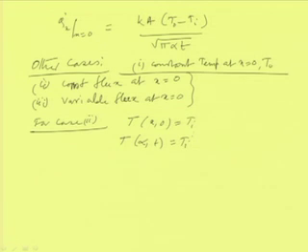So, there is no problem, these are not going to change. T at t equal to 0 is equal to T I, that is the initial condition, and this is boundary condition 2. Boundary condition 2 also remains the same, because the body is infinite in the direction of x. At the infinite direction, it is more or less like the initial temperature is not changing much; the change of the temperature is not felt. The other condition, boundary condition 1, is going to change.